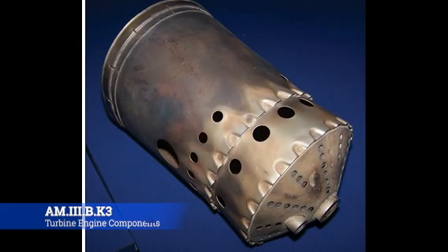This illustrates the annular combustion chamber liner. Some provision is always made in the combustion chamber case for installation of the fuel nozzle, and the fuel nozzle delivers the fuel into the liner in a finely atomized spray. The more the spray is atomized, the more rapid and efficient the burning process is. Whenever y'all do a fuel flow check on these things, you hold up a little Gatorade bottle or whatever to catch the fuel. You'll see it's like a mist. It's not even like a spray. It just kind of fogs fuel out, and that's to make it burn better.